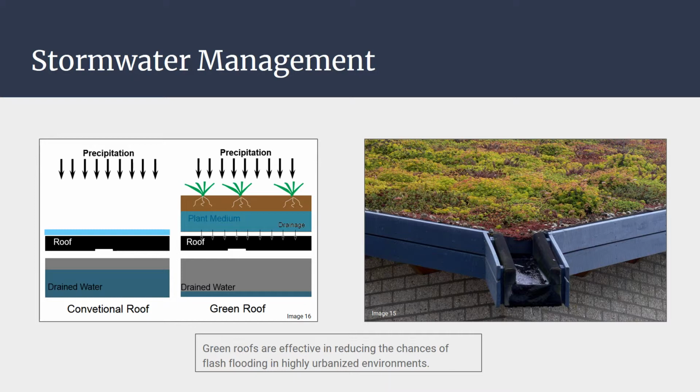Average runoff retention of the green roofs ranges from between 10 to 60%. That depends on the magnitude and length of rain events. Green roof systems manage stormwater before it drains off the roof, addressing the stormwater issue at the source rather than after the runoff has been collected.